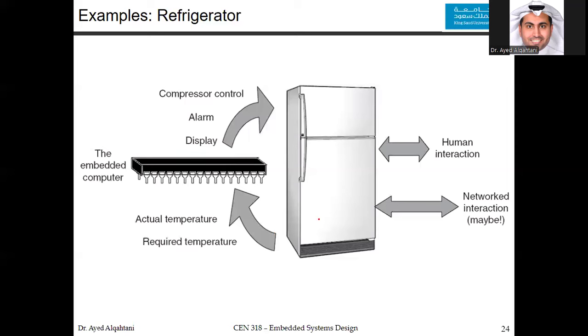Now, let's continue with the instruction cycle. Here we called them machine clock frequency and machine cycle. Now, when we say instruction cycle, this is the elapsed time for a microcontroller to complete the execution of a single instruction. So here we are interested in the instruction execution, which includes fetch, decode, execute, and write back of the results. Again, the reciprocal of the instruction cycle is the instruction frequency, which is the rate of instruction execution in a single second. And usually it's also measured in megahertz, like the machine clock.